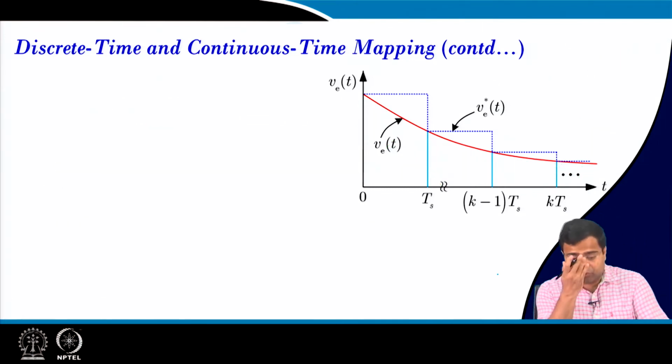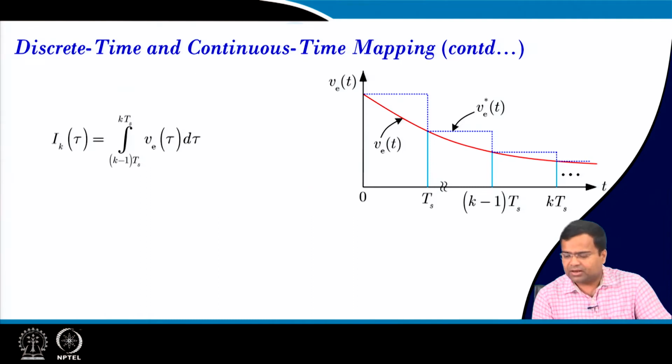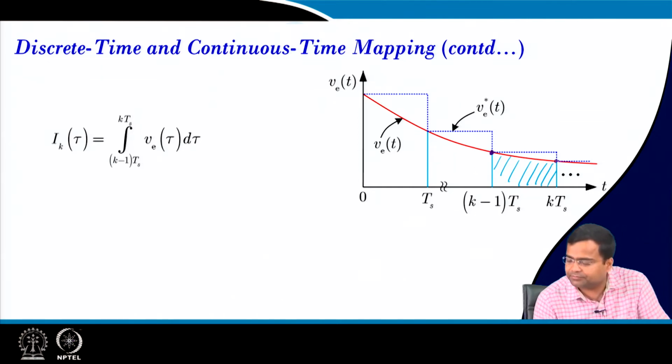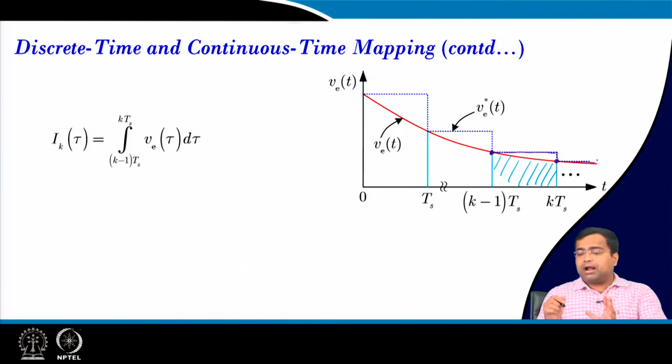Okay. Now, we want to find this exact integration, but if we sample it, then we will only have the sample information. That means for the digital control, or maybe for the A to D converter or sampler, after the sample and hold block, we will only have this information, that means sample then hold, sample then hold, but we will not have any information in between two samples.